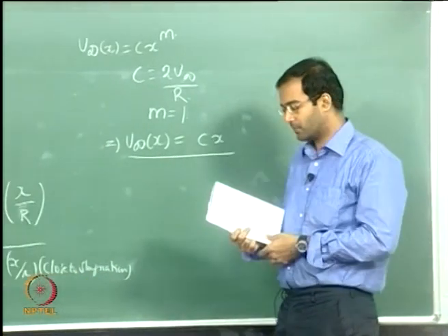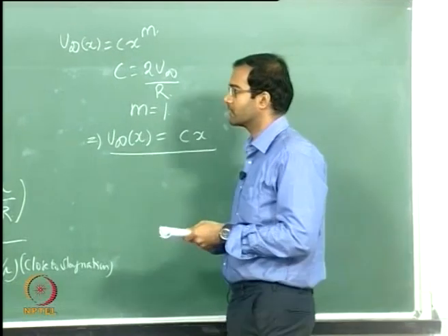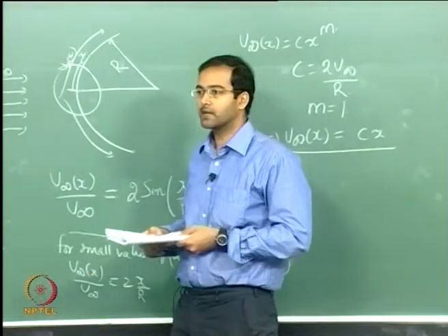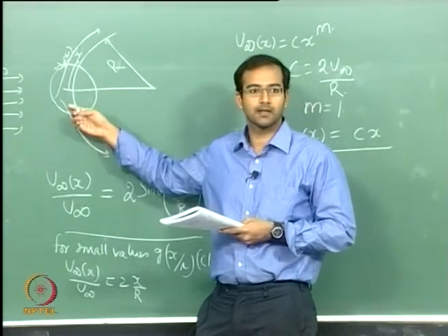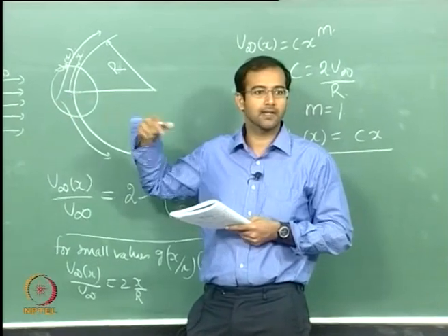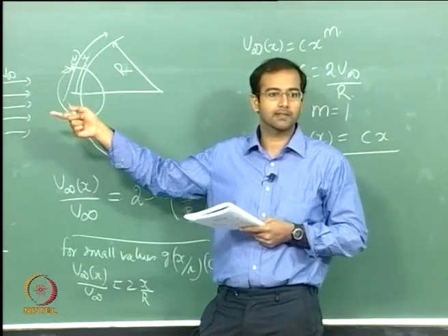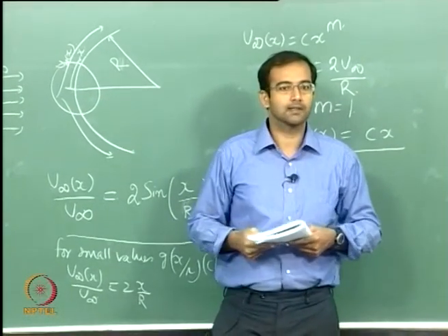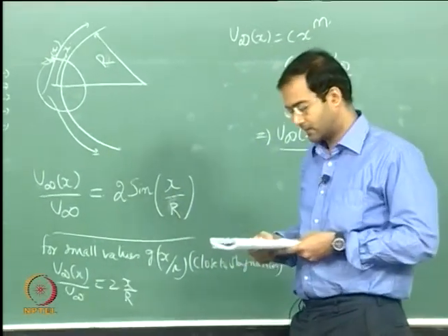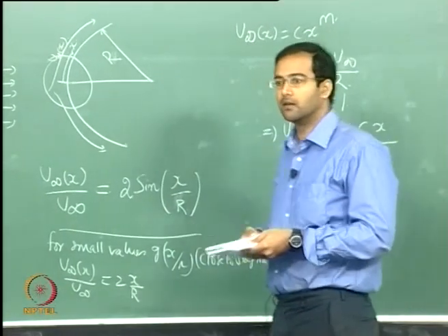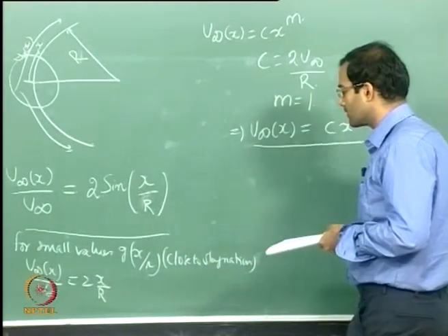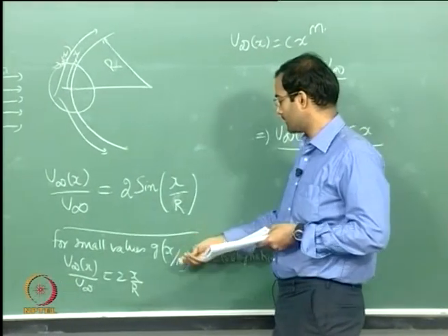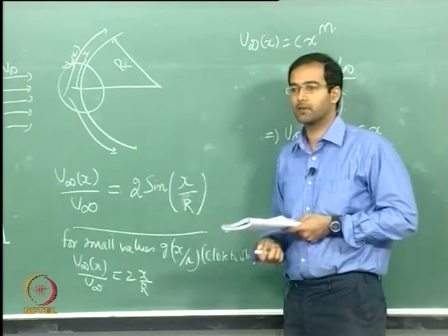This is a very useful correlation, because to calculate, for example, the heat transfer in the stagnation region of a cylinder, you can solve the energy equation from the Falkner-Skan solution and apply that to get the local Nusselt number profiles for the cylinder. So for small values of x your sin theta can be replaced as theta, right?